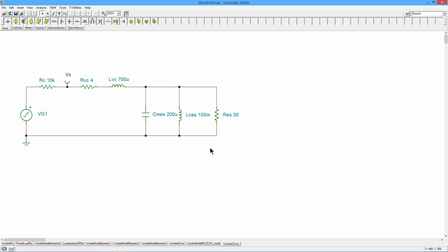All right, so the first measurement you probably want to take, you might want to just get a DMM and measure the voice coil resistance, right? Get that RVC value, get that out of the way. Then you drive this with your function generator, plug this into a digital scope, and you can just see the waveform.